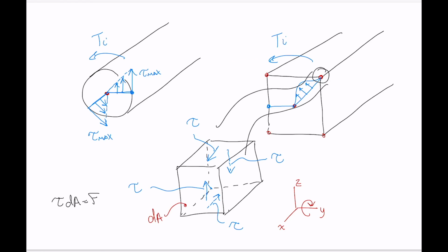So this happens whenever you have shear stress. Whenever you have shear stress in one direction at a point or on an element of material, you have shear stresses in 3 other directions. And those are called complementary shear stresses, and they're required for static equilibrium.